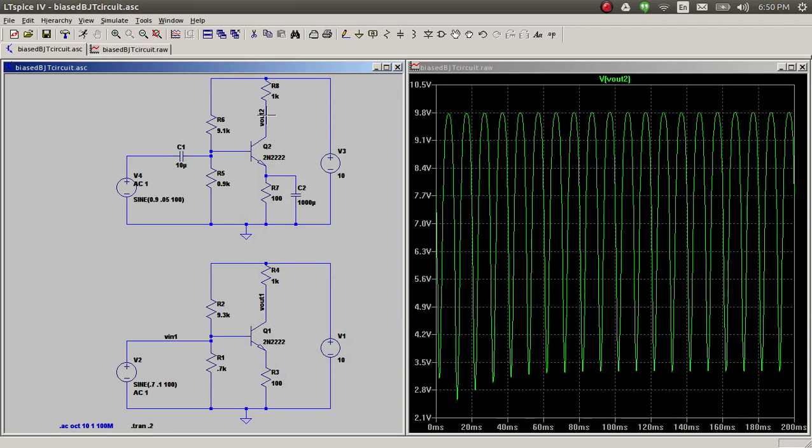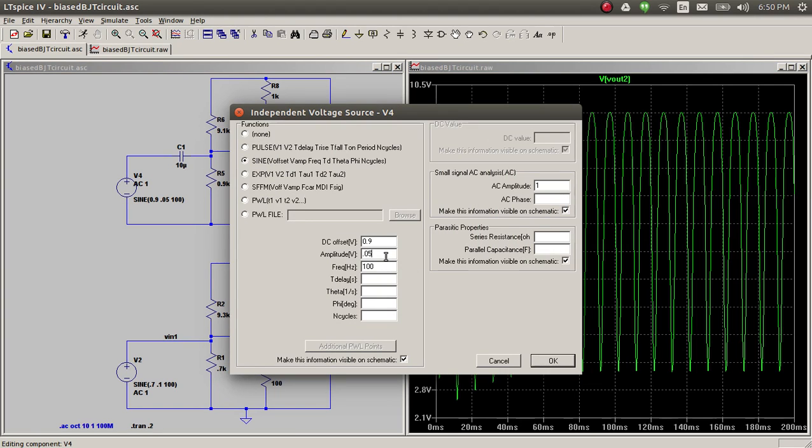and we look at the output, well, you can see that it's distorted, it's hitting the top because I only had a DC voltage of around a volt, about 2 volts, so 4 volts is too much, so it's looking fairly distorted. So I need to, this part is something you cannot figure out from the AC simulation.